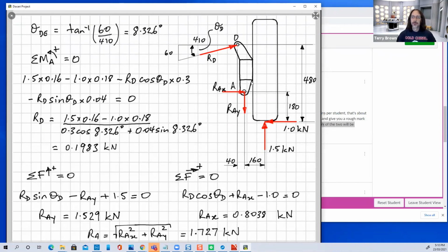Whenever you have, and it was the same in all of those tutorial and example quiz problems that we did, exactly the same thing, whenever you've got 2 bodies connected together like this, and you imagine you separate them in your free body diagram, let's say you draw the free body diagram of this one, because there's some forces up here and this here is reacting against them, you'll have reaction force, let's say X and Y on here.